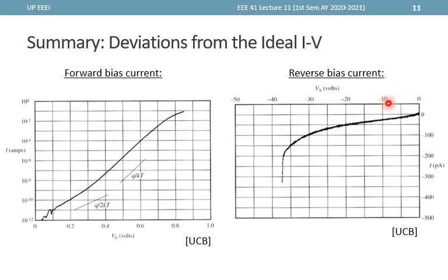If we increase the reverse bias voltage, then the depletion region widens, and the wider the depletion region is, the more area or space in which the carriers can be generated. And the larger that area is, the more carriers generated, and the more added reverse current we have.